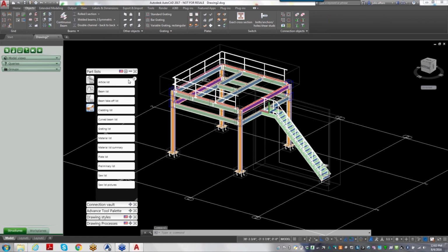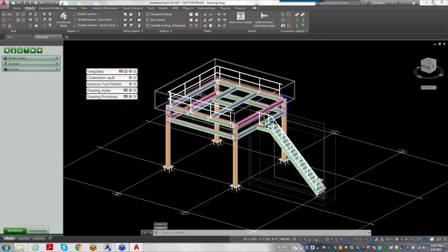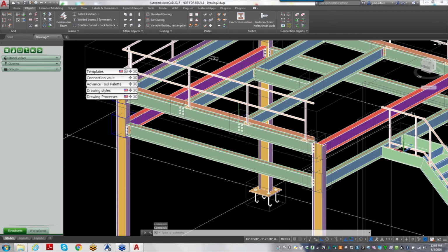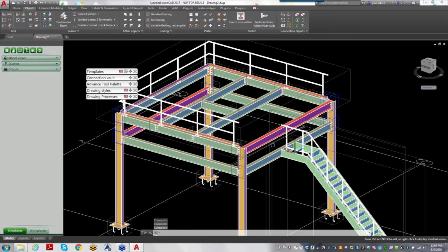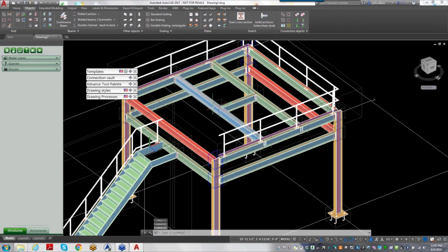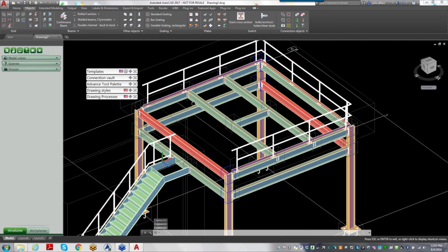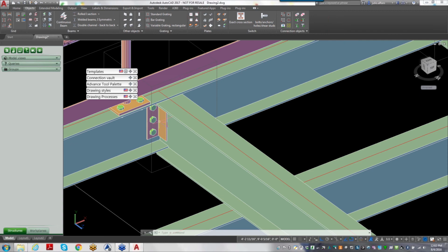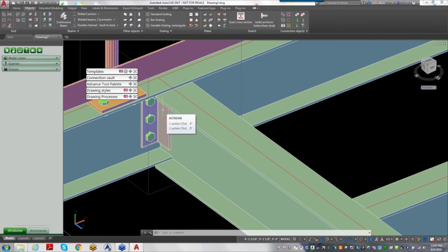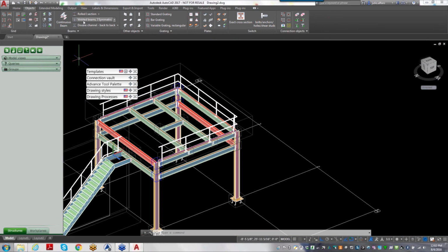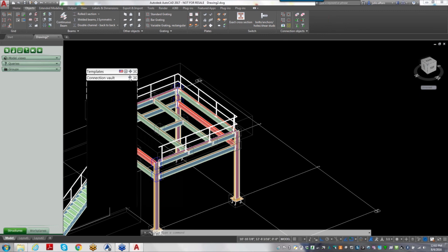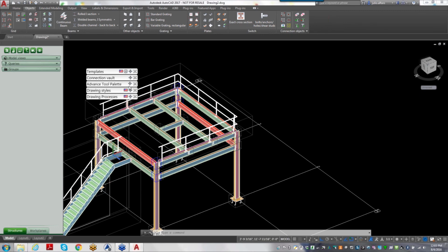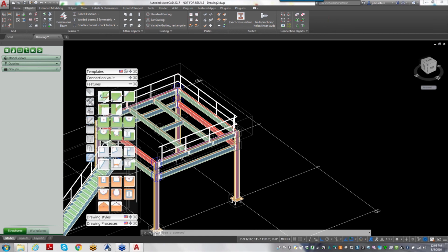One of the things, and I'm a new Inventor user, I don't know how much it's changed, but what you gain in Advanced Steel that's different from the frame generator, obviously, is the connections, right? You can do welded connections. If I were to do a frame here, I can actually go into this pattern here and start creating some welded connections.